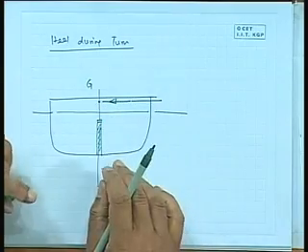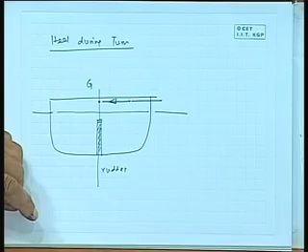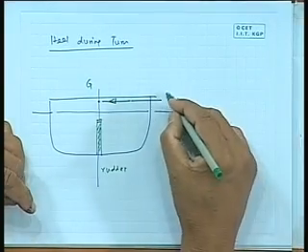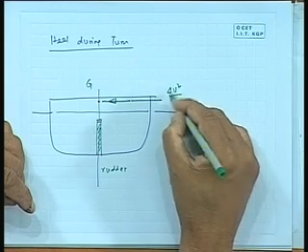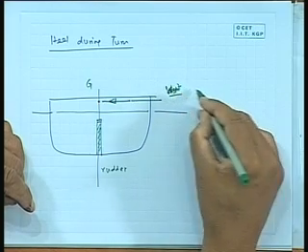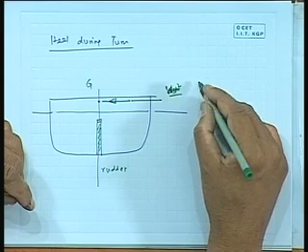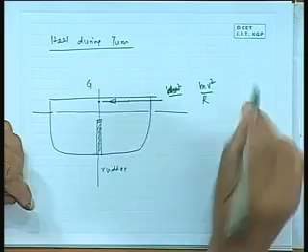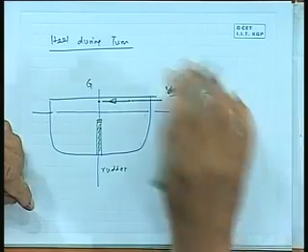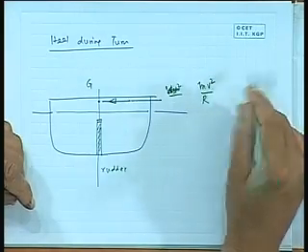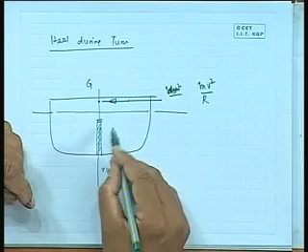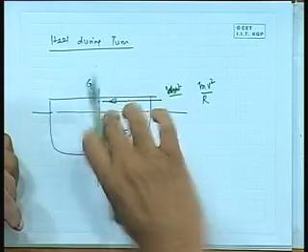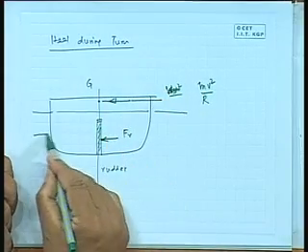Now as it turns, as you know, you have to have here a centrifugal force, and this force is delta V square by g, where delta is actually weight. In fact, I like to write mass, or mV square by R, M being the mass of it. Okay, and you have here a rudder force Fr, because it is turning this side direction, and a reaction force Fh.